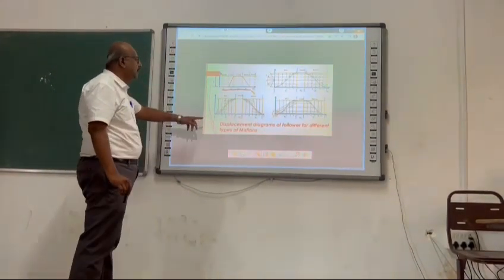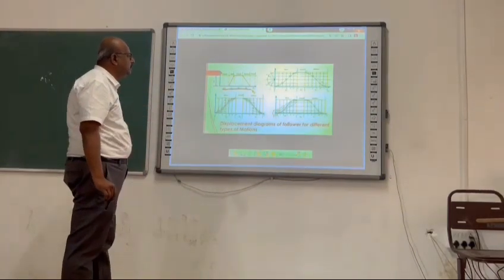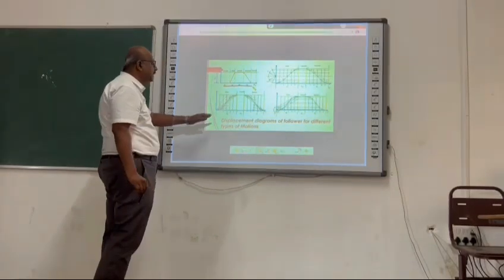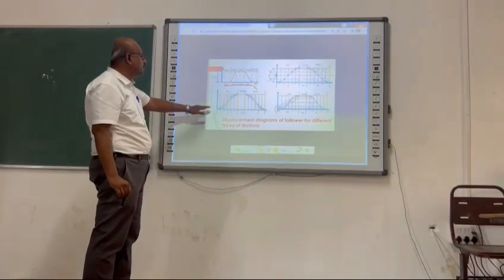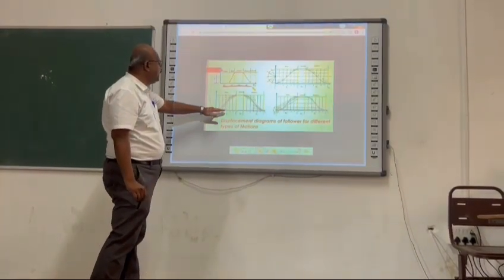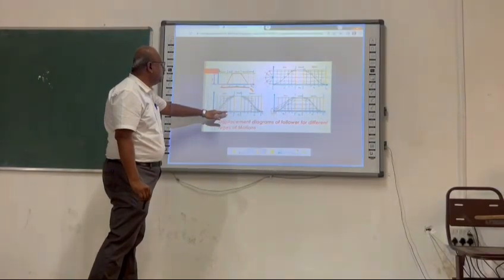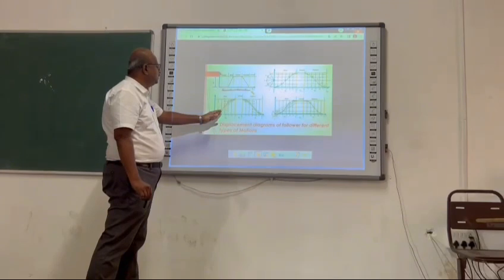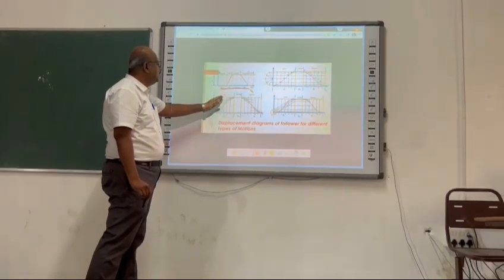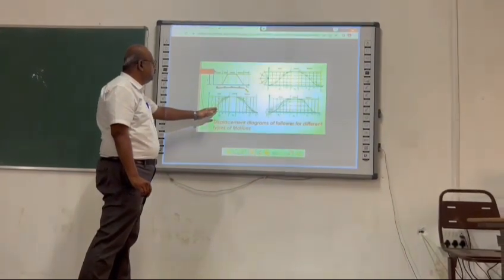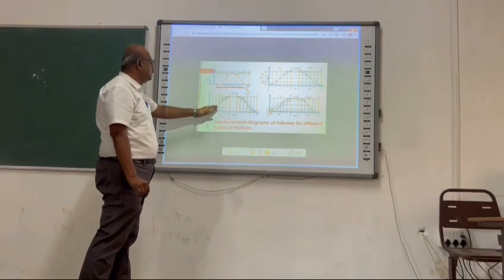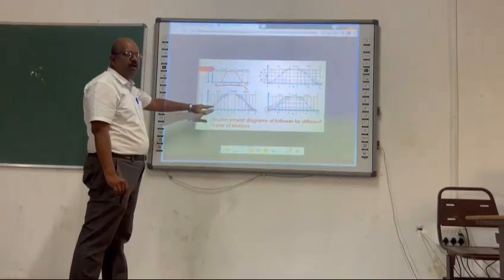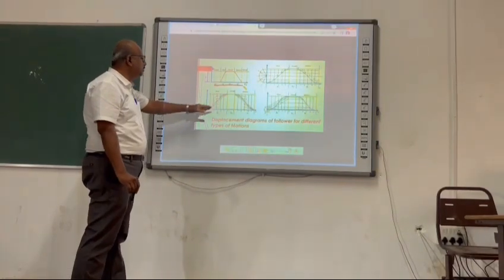For uniform acceleration and retardation motion, the following procedure is employed for constructing the displacement diagram. First, the rise period is divided into an equal number of parts, and the midline in the vertical line, the midline of the portion, is divided into the same number of equal parts.